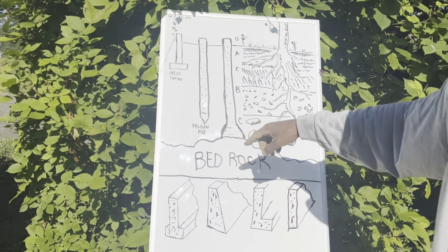Now, since you're a carpenter, and we focus here on this channel mostly on residential, I want to show y'all these basic or simple types of residential or light commercial foundations. These are section drawings. So this would be called an inverted T. This would also be considered a shallow foundation. Something like this caisson pile would be considered a deep foundation. But this right here is basically used for residential. This is an inverted T foundation. This will be very common.